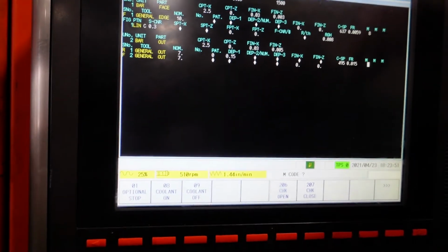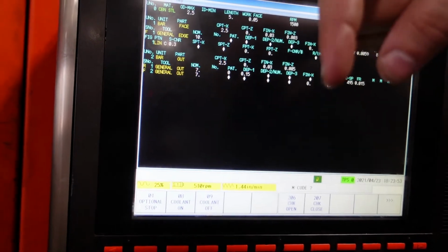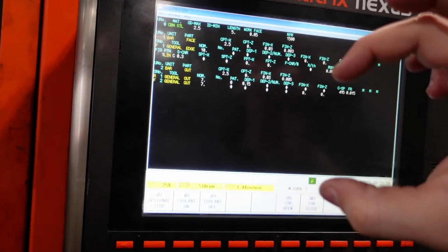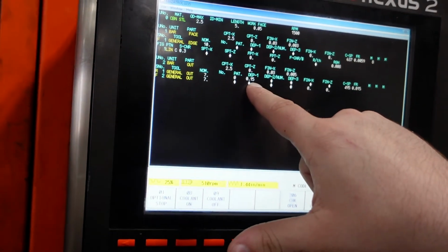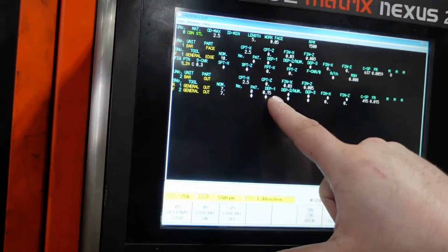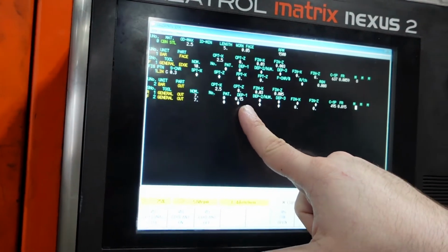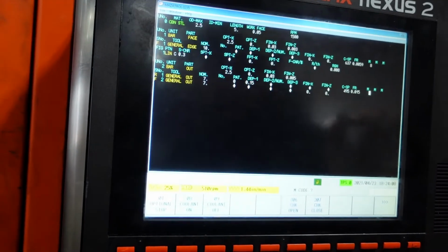So we'll take a 150 thou depth of cut, and this is depth of cut radially. This is not depth of cut on the diameter. The diameter will change by 300 thou, not 150. This is a radial depth of cut. It'll almost always be a radial depth of cut, and that counts for mils too.